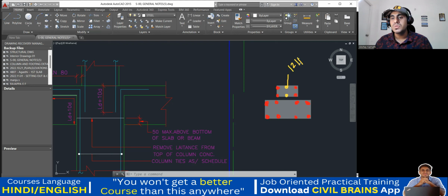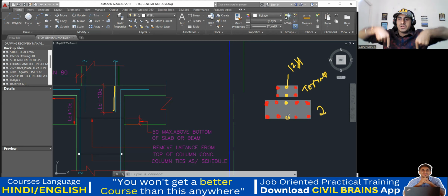So now what I'll do, this is my second floor, and this is my third floor. I'll say terrace floor. Now in this particular column, I'll bring additional bar of 12 diameter, and this much length, LD plus 10D, I'll insert it here in this column. It will go inside, and from here I'll take a 12 diameter bar. Understood the concept?